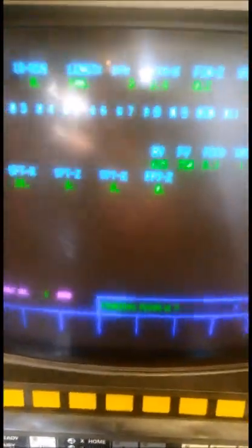So our starting point is our material OD, which is 31 for X. Our starting point in Z. Edge is different to all the other tool paths in that positive Z is out this way, and with all the others, positive Z is that way.